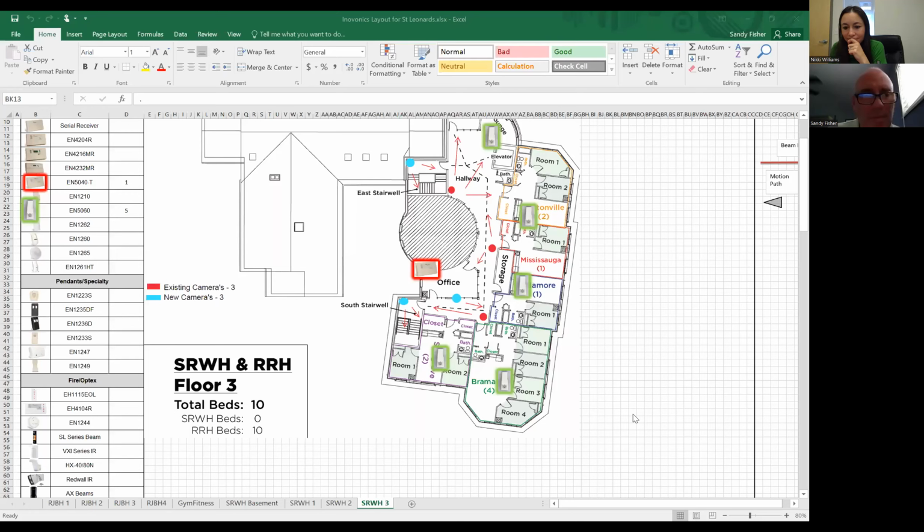Here's a site where we get a PDF of all the different floors. This site has 2 buildings and 4 floors on each building, and the dealer did a video design and gave me this. You use the snip tool on your computer, cut and paste that picture, which makes a PNG file, stick it into this spreadsheet, and then you can populate all kinds of Inovonics devices. So that they pop, I added a glow color.